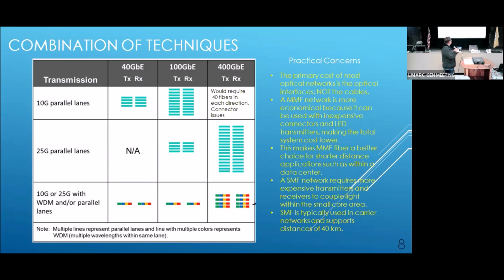To go to 400 gigabits, it's just not practical, because that means you need to jam 80 fibers into a single connector with precision and no alignment problems. Tough to do. The connector people have tried, and getting it to a reasonable cost is tough. Okay, then we have 25 gigabits, which is somewhat newer. You can probably tell that we're going to run into a speed limit with the fiber because of a chipset called the SerDes, which is a serializer/deserializer chip. These chips today are topping out somewhere around 25 gigabits per second.